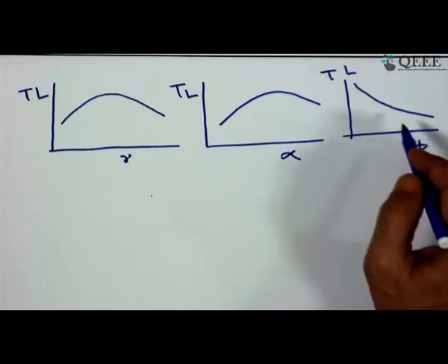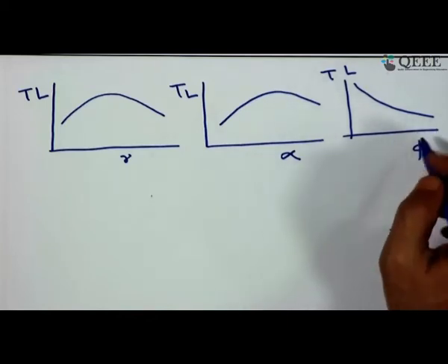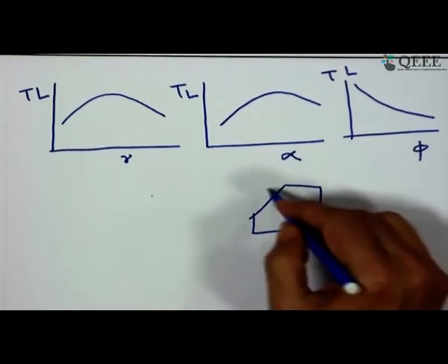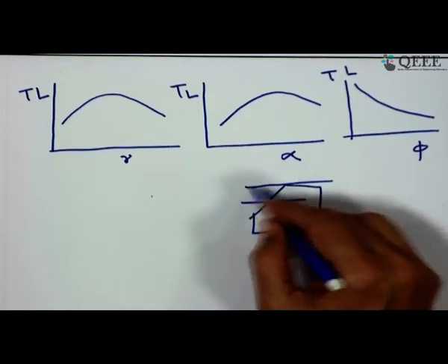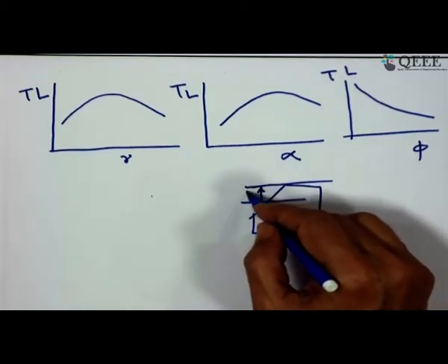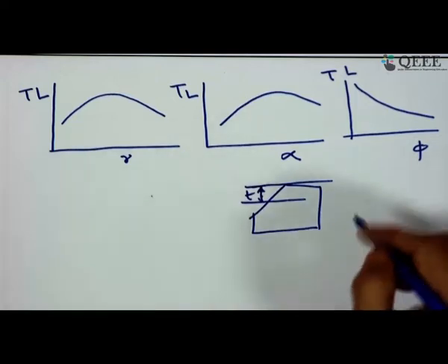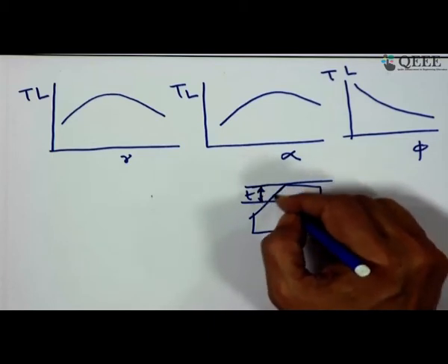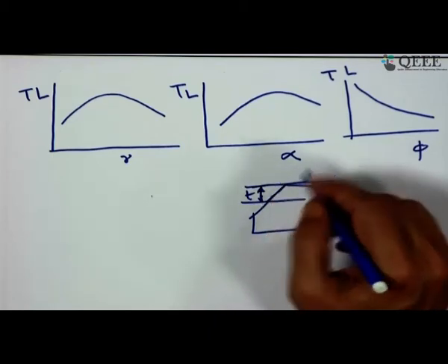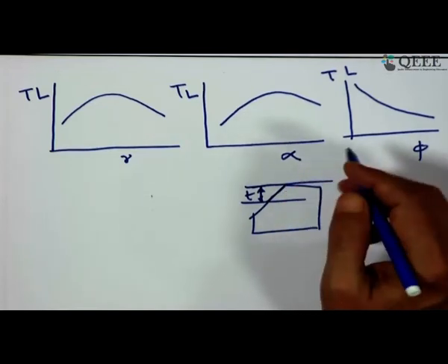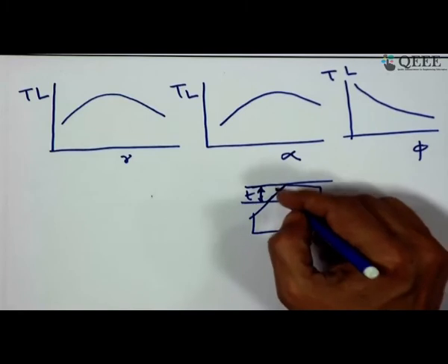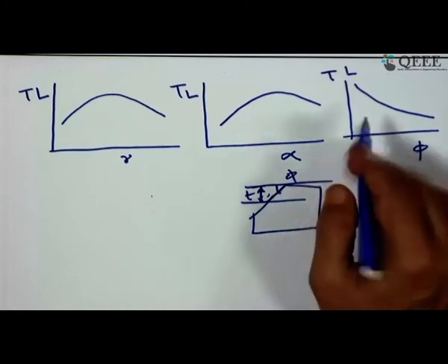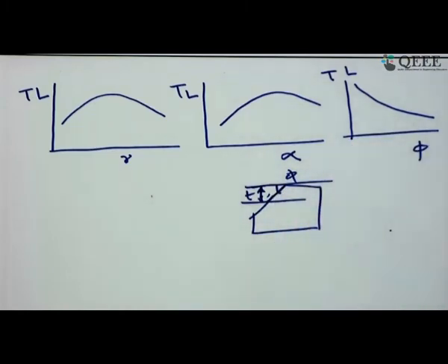But when it is phi, you can imagine A1 means S sin phi, and also the length of the active section of the cutting edge, which keeps on changing for a given depth of cut, and this we have covered. If you see the lecture of the previous class, you can immediately come to that conclusion. So, for the same depth of cut, you can have larger width of cut, and larger width of cut means thermodynamic load per unit width of the cutting edge will be reduced, and this is very much connected with, that means higher the value of phi, that will lead to higher temperature and loss of life of the tool.